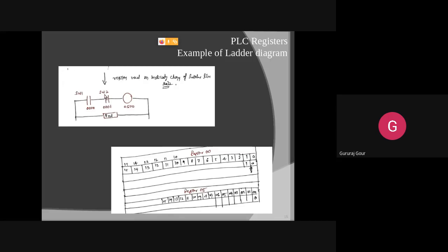So you can see here two inputs are written with addresses and the output has its own another address. It is also having its own numeric address. So register 00 will be represented like this and 05 will be represented like this. With the help of such an arrangement of registers, which are used to hold these addresses, and with the help of programming, we are going to control the switches or inputs and the output solenoids like this one.